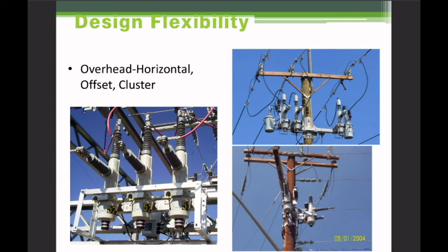Oh, it can do some software magic there in terms of automatically reconfiguring the system by knowing which side has voltage on it. So if there's an outage over here and it knows that, and it can figure out that there's no fault down here, but there's voltage here, the switch can automatically close to allow energy to flow through, for example.